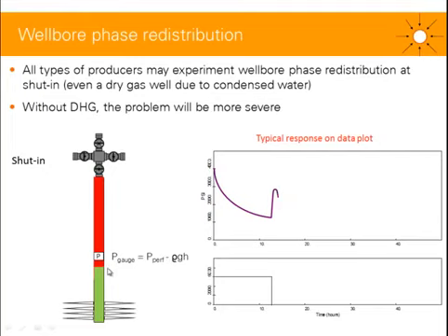If the gas-liquid interface stabilizes below the gauge, or even past the gauge, then the density below the gauge is going to be constant. Okay, so this term is going to be constant, and now the pressure at the gauge will be again a direct measurement of the pressure of the perforation. So we will end up with a true PBU response.